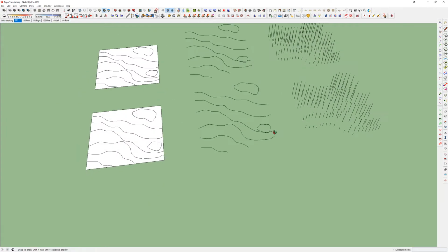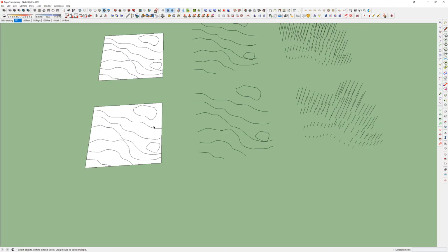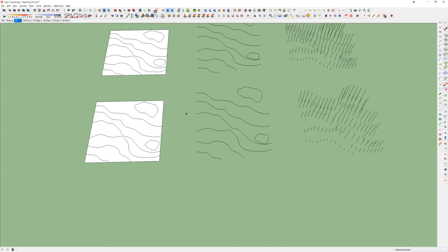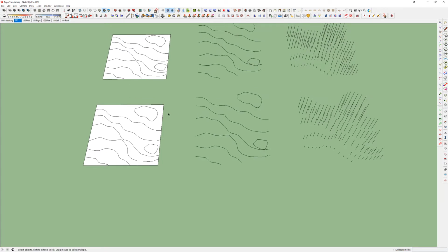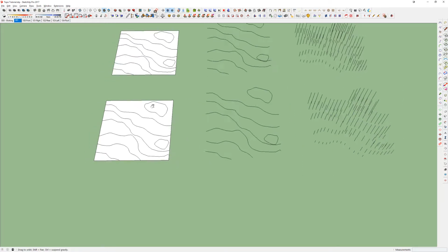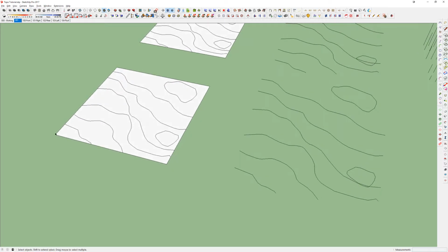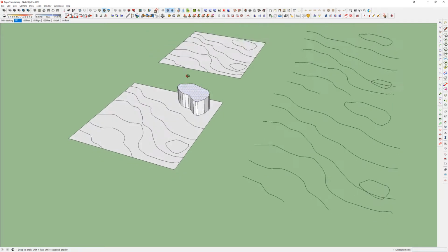This set of topography is just something I quickly created here in SketchUp. It's not anything real, but what I wanted to show is that you can essentially make the same exact topography no matter what you get. And we can actually build all of them at the same time. If they ever come in like this, I just draw a box around it and make your faces. And then from there, you just extrude up to the heights that it's supposed to be at.